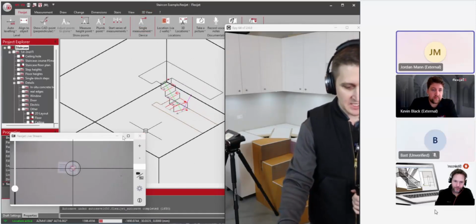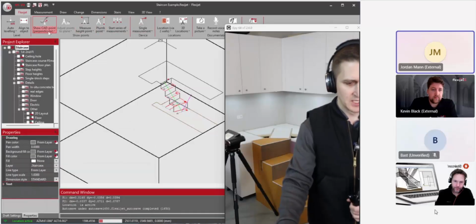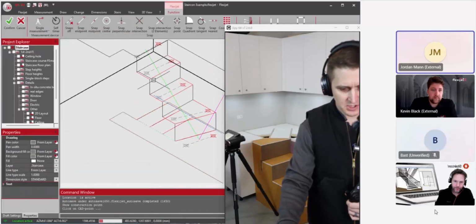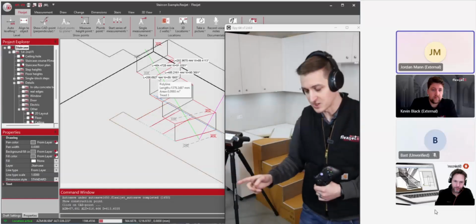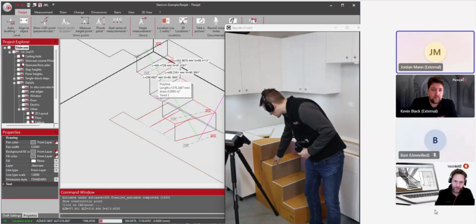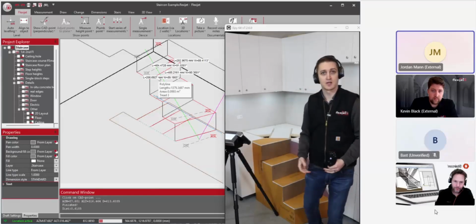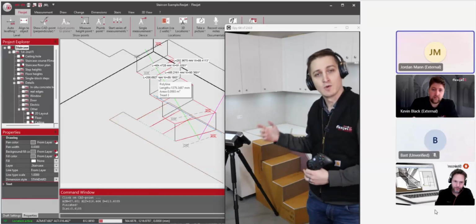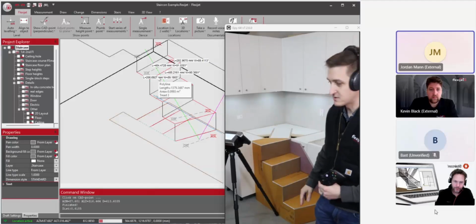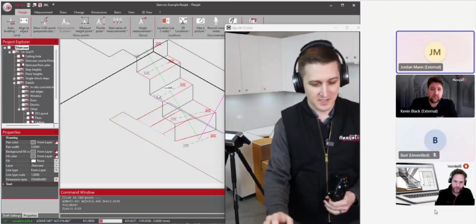And so now Flexijet knows where it is. We're back in our same measurement. Flexijet's in a different position. We can confirm that by asking Flexijet to, for example, show us a known corner. We knew where this corner was when the Flexijet was in another position. When we return, whether it's an hour later, or whether it's 1 week or 1 month later, and we resume the location, Flexijet can give us positive confirmation there by pointing back to one of those points.